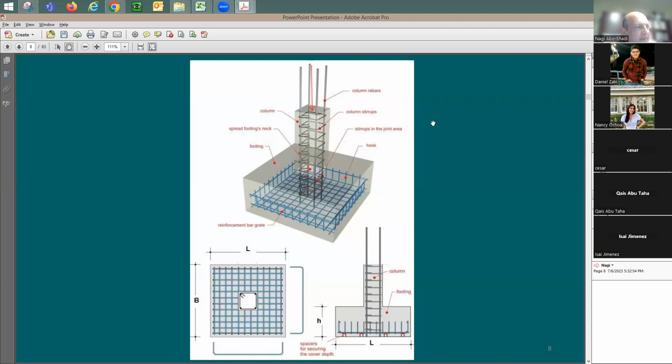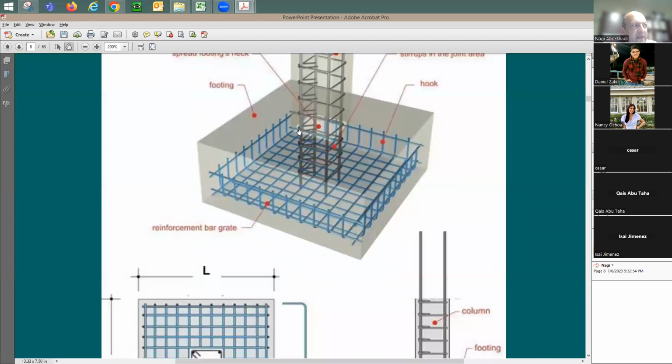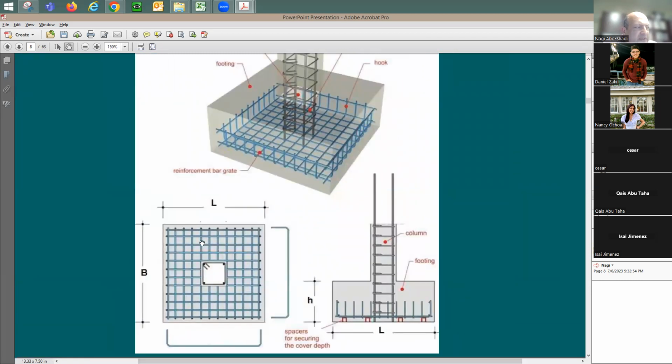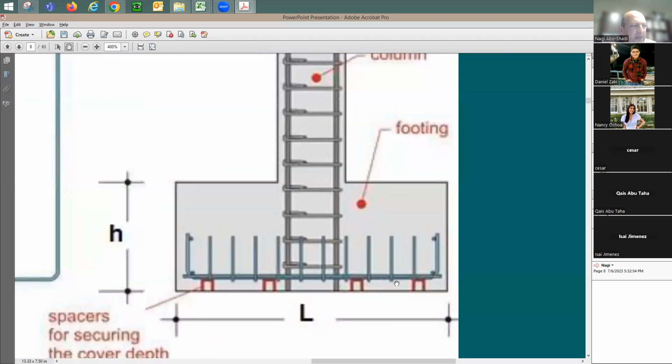No question. Now, in the footing itself, I'm going to put the reinforcing. And if you look at this, you have a mesh in both directions. And you see here, the reinforcing is mainly at the bottom. I'm wondering, do I need the reinforcing to be at the top or the bottom of the footing? Let's give it the total thickness of the footing from here to there. But the reinforcing itself is placed at the bottom. We look at this section here. Here's a plan. It shows a mesh in both directions. And look at this. Main reinforcing is going to be at the bottom of the footing.